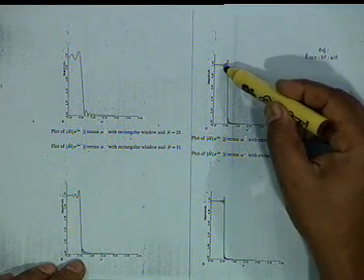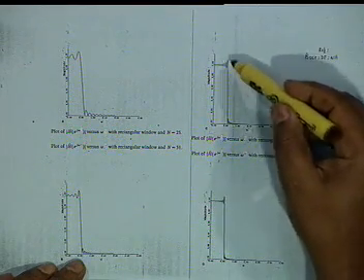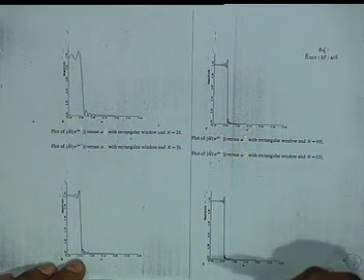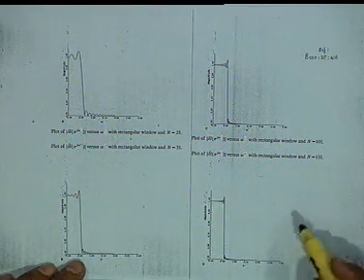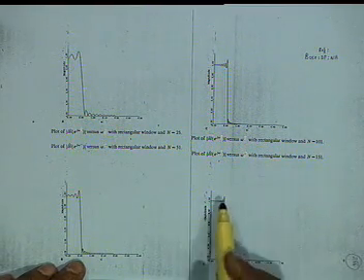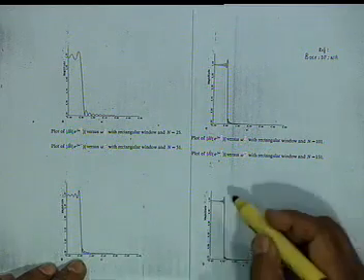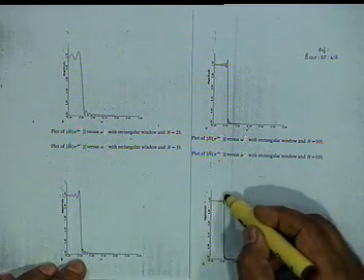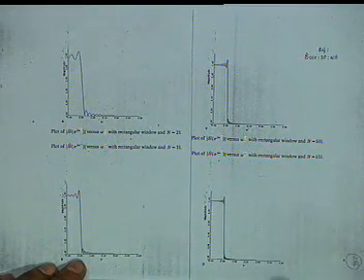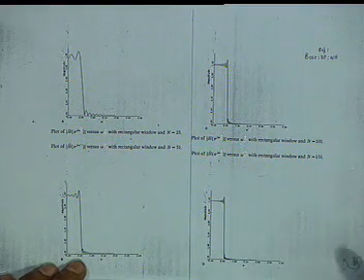You see there are more oscillations here, but this amplitude and this amplitude remain the same, and this is 151. When you go to an infinite number of terms, it will come straight, oscillations will hardly be detectable, but there would be a rod here and a rod here. Okay? So this is what Gibbs oscillation is, and therefore we need to do something about the window.